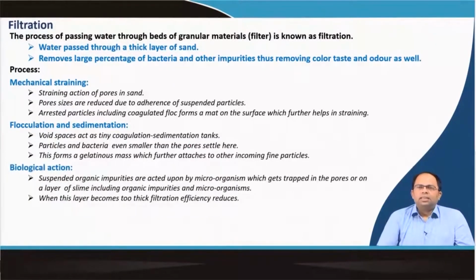Then biological action happens. This coagulant sedimentation area has this particular film, and suspended organic impurities are acted upon by microorganisms which get trapped in the pores, or particularly on the slime that we talked about just earlier. These microorganisms act on the organic impurities and are able to break them down further. Eventually this slime layer gradually becomes thicker and thicker,